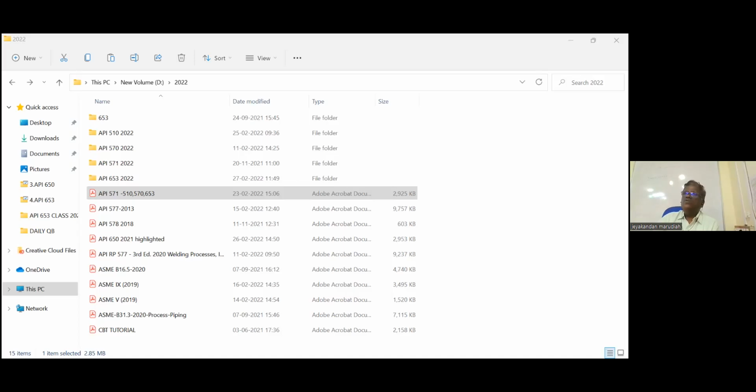Okay. How will you identify the nickel-based alloys? Alloy with a 3-digit number. Alloy 200, alloy 400, alloy 600, alloy 627. Alloy with a 3-digit number is considered a nickel alloy. Okay. These are the things we should know in the terms and definitions. Now, come to the damage mechanism. So storage tanks, the advantage is generally they are not operating with high pressure. They are not operating with very high temperature or very low temperature.